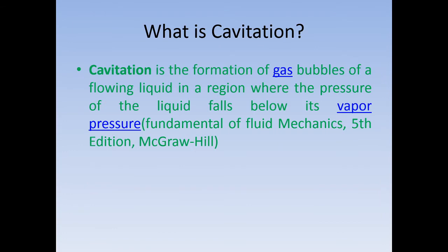So what is cavitation anyway? Cavitation is the formation of gas bubbles in a flowing liquid, in a region where the pressure of the liquid falls below its vapor pressure. So it creates bubbles. Bubbles mean some of the water is no more in the liquid state but already in the vapor state.